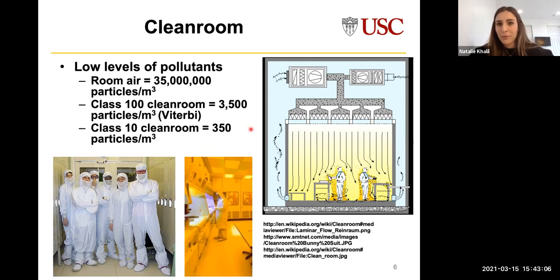Okay, so how does a clean room work? Essentially you're just filtering out particulates from ambient air using a series of HEPA filters, which we've talked about in our biosafety cabinet cell culture lecture. So this is basically just filtering out particles by size. And once air enters this clean room, there's also airflow directed towards the ground and towards these exit vents. And this minimizes the amount of dust and particles that are freely floating in the air